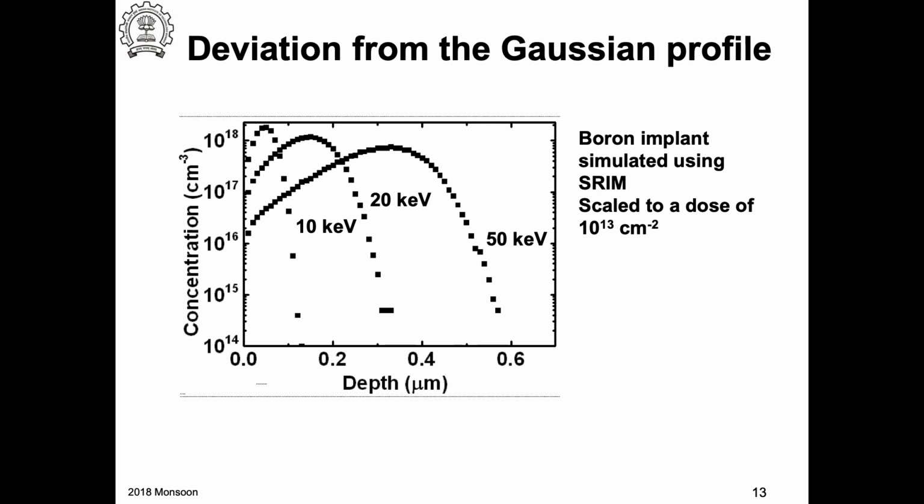Okay, so I have the junction here, and I would really like to get this exact profile. One of the ways to measure the doping concentration, and I have many methods, like secondary ion mass spectroscopy, SIMS, or I can do what is called electrochemical capacitance voltage measurements and find out the doping profile. And then I use these doping profiles in my actual simulation. Okay, so that is one possibility.